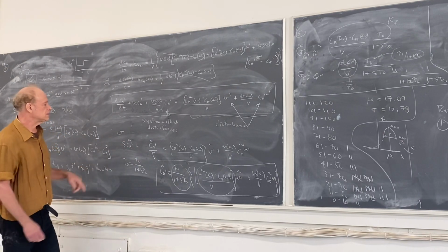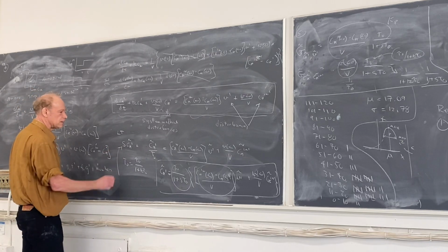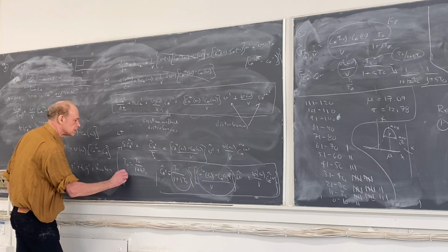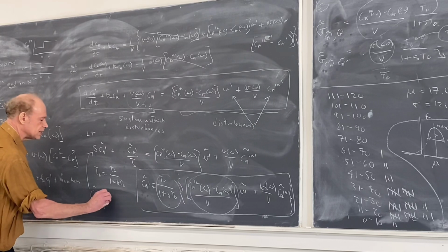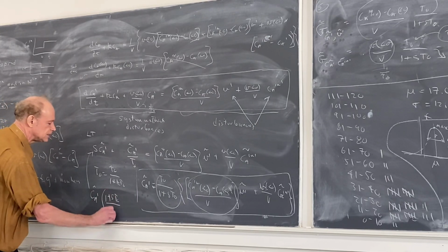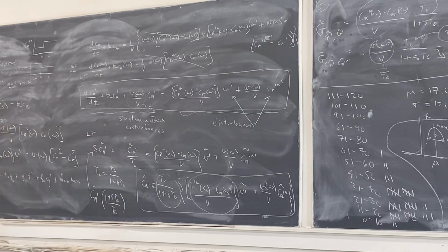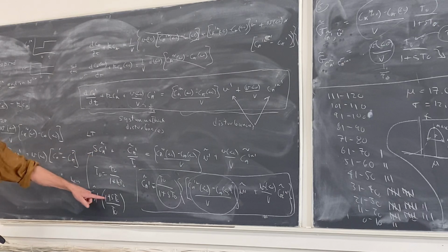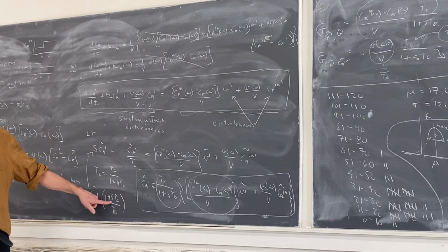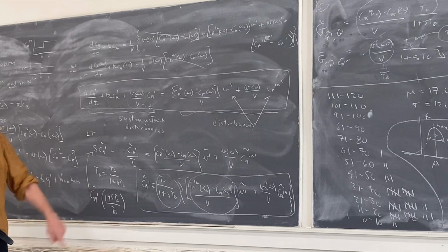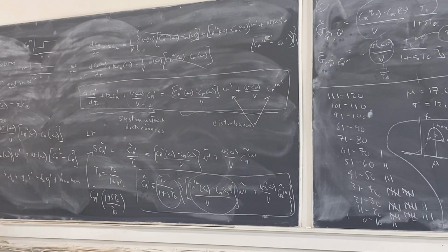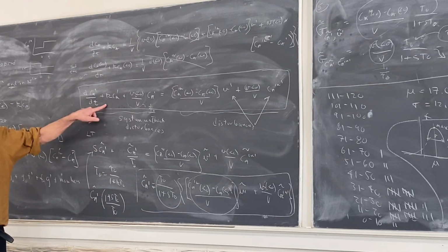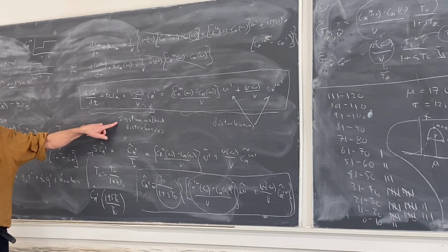So notice this thing, the left-hand side, was Ca prime tilde times 1 plus s tau 0 over tau 0. This thing is a polynomial in s. It's just a linear polynomial, but it's a polynomial in s. And the polynomial in s that comes from the left side, that comes from the system without disturbances, is called the characteristic polynomial.